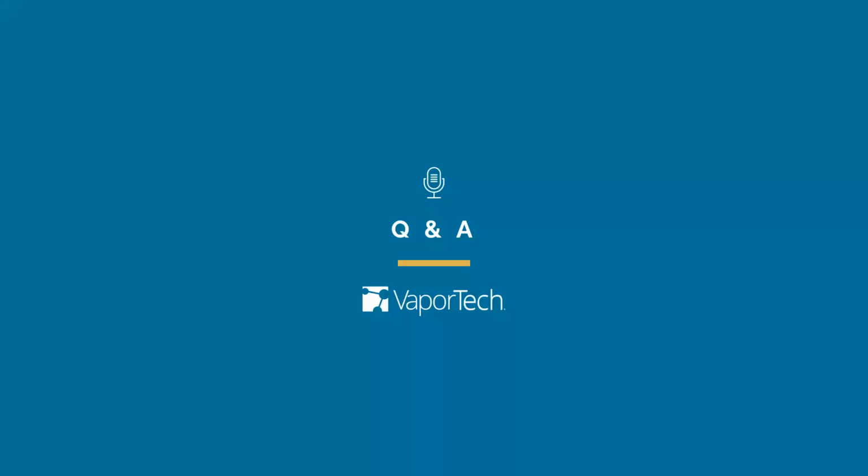Start with solvent is always a good choice. Vapor degreaser sometimes helps, but you may have to actually use mechanical cleaning, meaning manual cleaning, if you have issues with difficult geometries, as you put it, if you have pockets, undercuts, or channels and all of that. You may have to do manual cleaning first before you even go into a degreaser, for instance. But yes, there's no easy answer to that question.